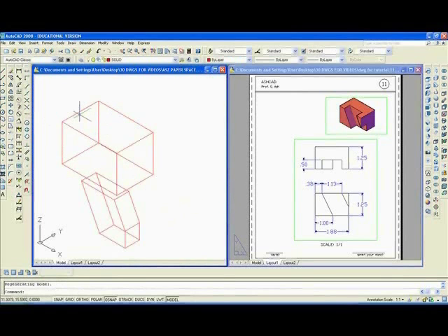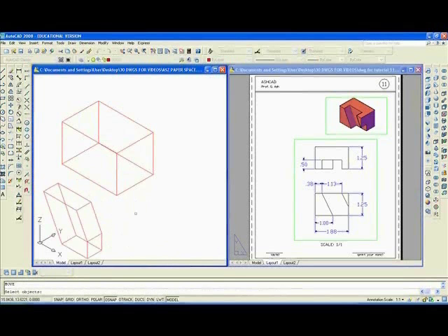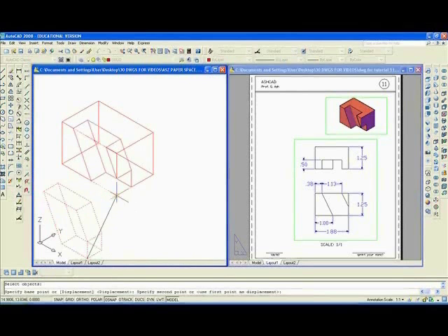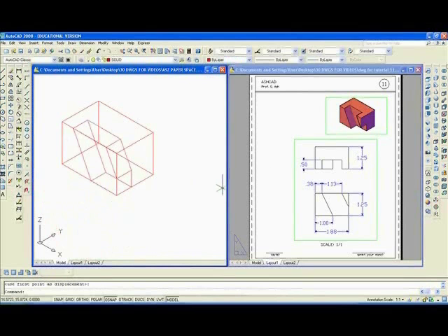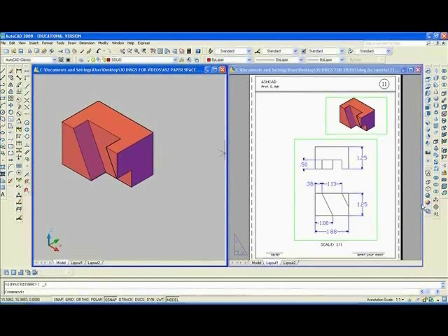and we'll want to move, M, enter. I'm going to move that, and then I'll move it again, because this corner here is supposed to fit in that corner, and you'll want to subtract from the rectangle, enter, that shape, enter, and let's see what it looks like. It looks correct, so we'll zoom extents, Z, enter, E, enter,